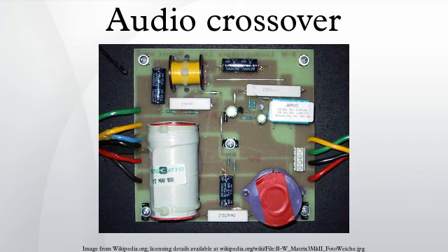The low-pass filter presents a high impedance to the signal, and the tweeter presents a low impedance. So the signal passes through the tweeter. The signal continues to the connection point between the woofer and the high-pass filter. There, the HPF presents a low impedance to the signal, so the signal passes through the HPF, and appears at the lower input terminal. A low-frequency signal with a similar instantaneous voltage characteristic first passes through the LPF, then the woofer, and appears at the lower input terminal.